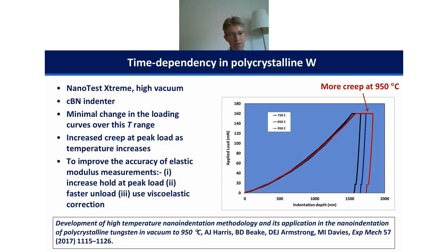And if we want to improve the accuracy of our elastic modulus measurements, we really need to come up with some strategies to mitigate this enhanced creep at high temperature. So I've put some of them there. For example, we can increase the hold at peak load. We can combine this with a faster unload, and we can also combine it with a viscoelastic correction to the unloading data.